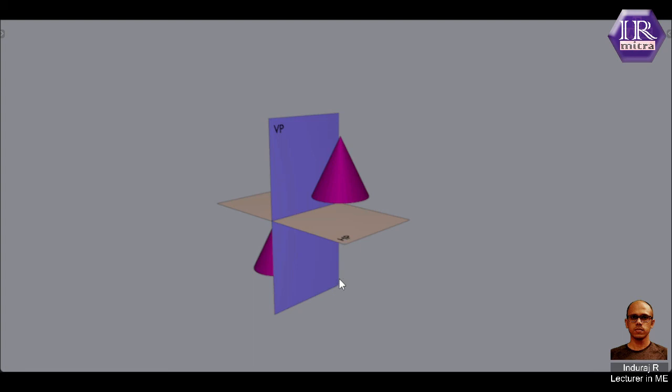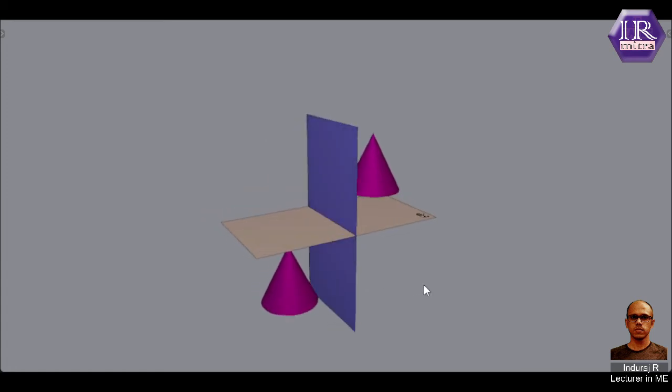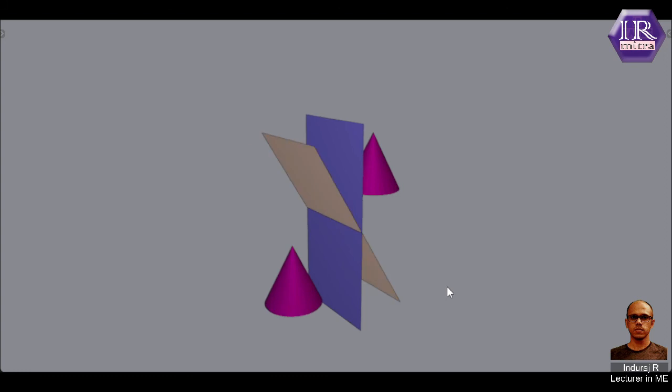The rule for rotating HP is the same in any quadrant. Even if it is in the second quadrant or in the fourth quadrant, the HP should be rotated in the same manner. So just imagine it is in the second quadrant and there are two views in the HP and VP, forget about the names. Then if we rotate that HP in the clockwise direction like I discussed earlier, the two views will merge with each other. So what can we deduce from that combined view of an object? We can deduce nothing from that.